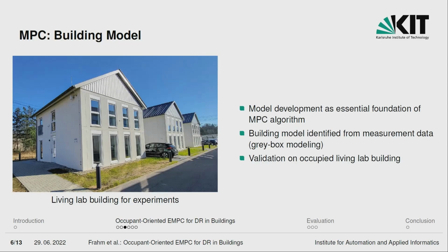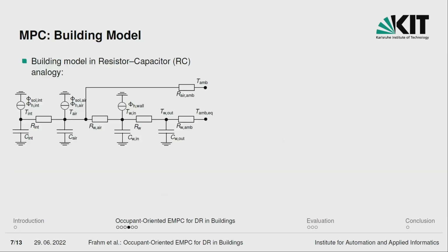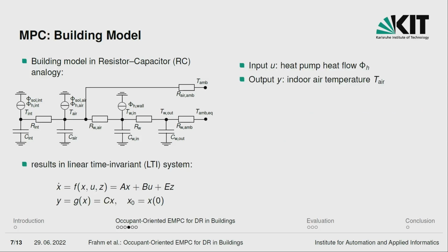As an essential part of the model predictive control design, we develop a thermal building model. We identify it from measurement data and validate it. The model is designed in a resistor-capacitor analogy, where the main input is the heating and the output the air temperature.